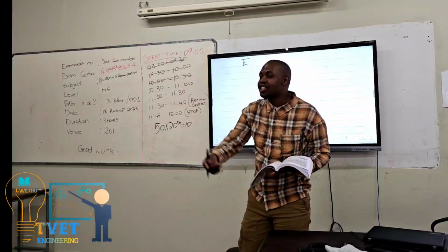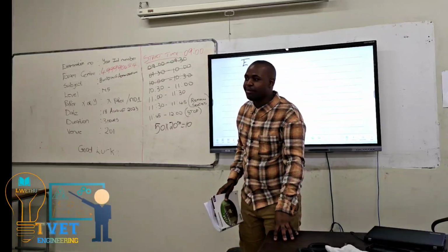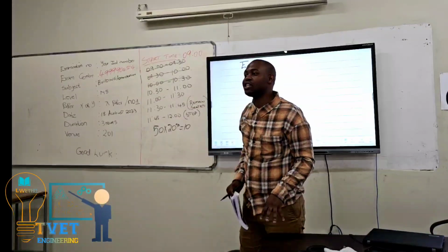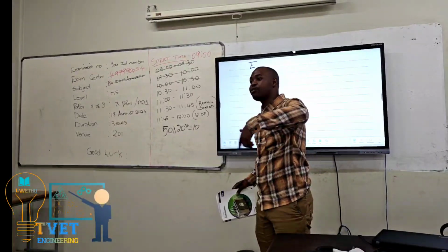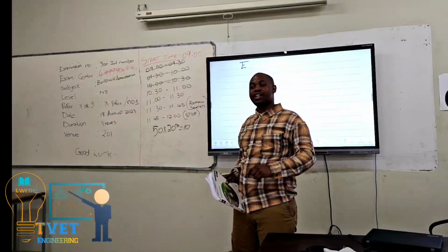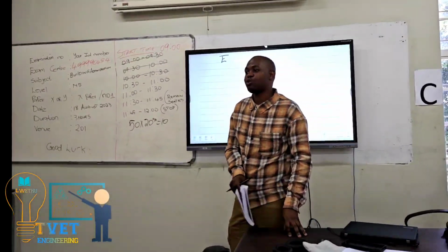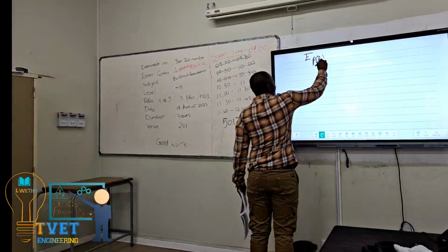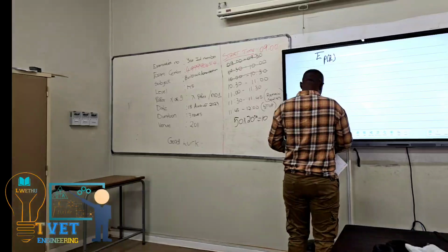The faster the stator magnetic field cuts the rotor at synchronous speed, the more EMF is induced. Remember, induced EMF is correlated to the rate of change of flux, according to Faraday's law. So the rotor EMF, as a rotating value, is equal to s times E2.